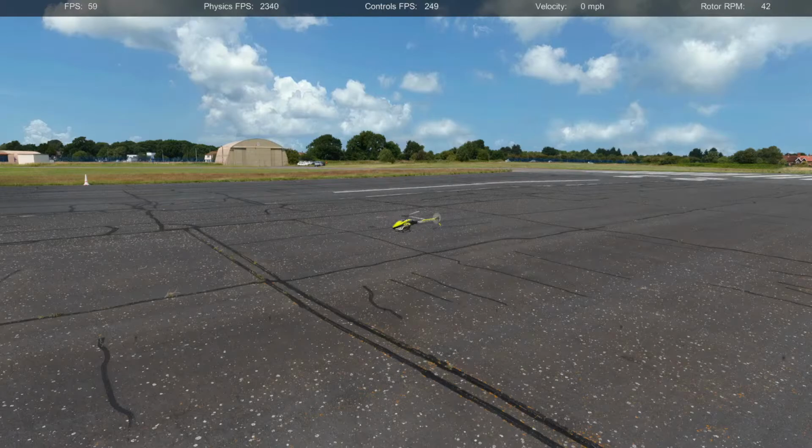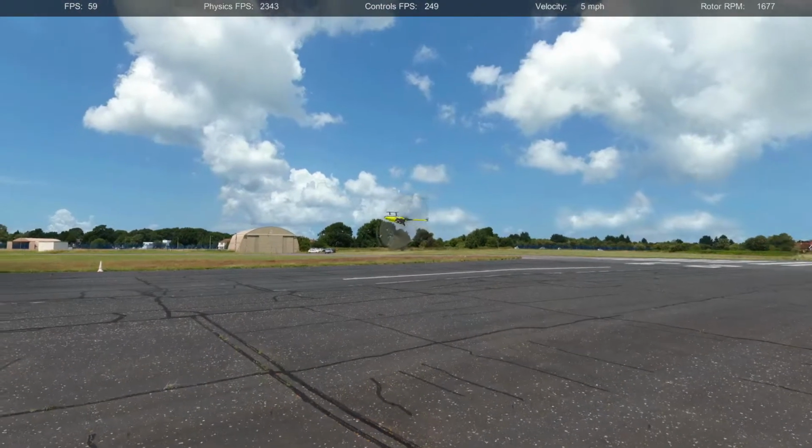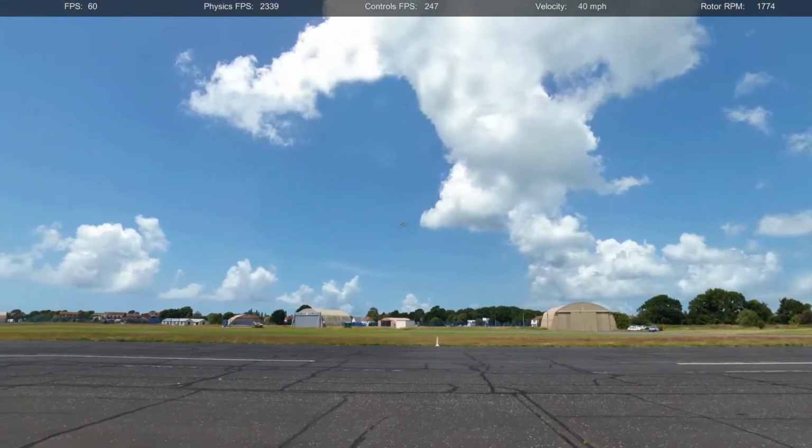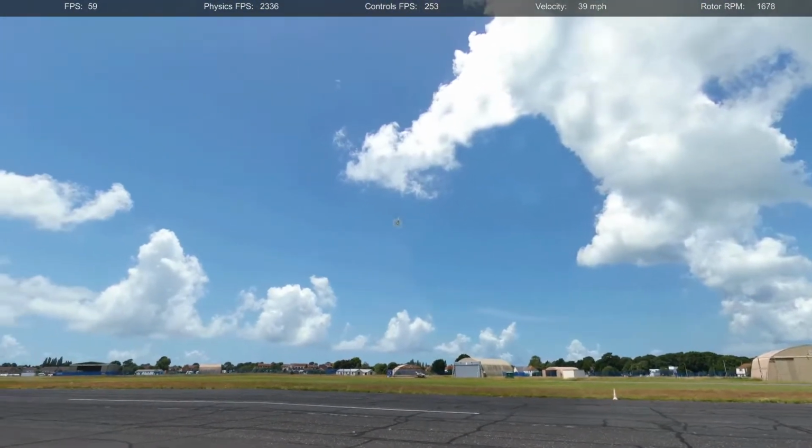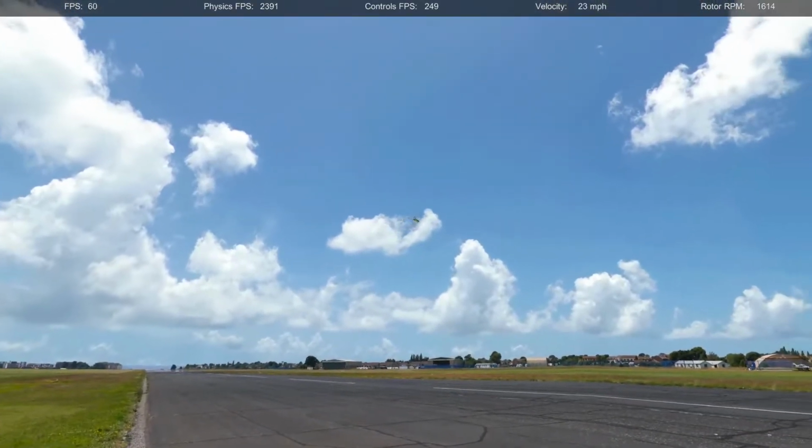All right. We do use our elevons. We like more span further out. Again, you want to get away from that tip vortex and capitalize as much on the upwash out there at the tip from that vortex.